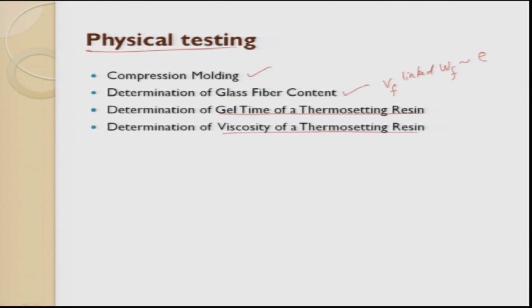The gelling time, what is gelling time? Gelling time means a liquid is slowly moving to a solid. It is getting into a term in between, called gelling. So, what happens? The viscosity changes, from low viscous liquid to high viscous. So, it is good to know what time the gelation starts, and once it starts forming, how the viscosity changes, such that I can use the same polymer to make a sound product with reinforcement.